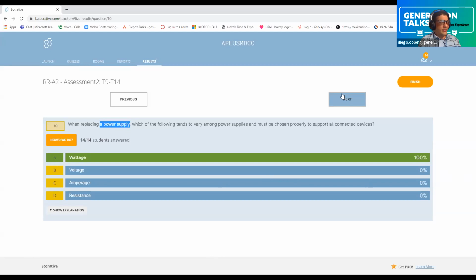Sometimes they put a nice little label that will be in volts and amps, or they'll even be cuter and give you the actual watts. Be very careful, because sometimes if they do give you that information, it will contain the 110 number and the 220 number. Therefore, you need to make sure which calculation you're doing.